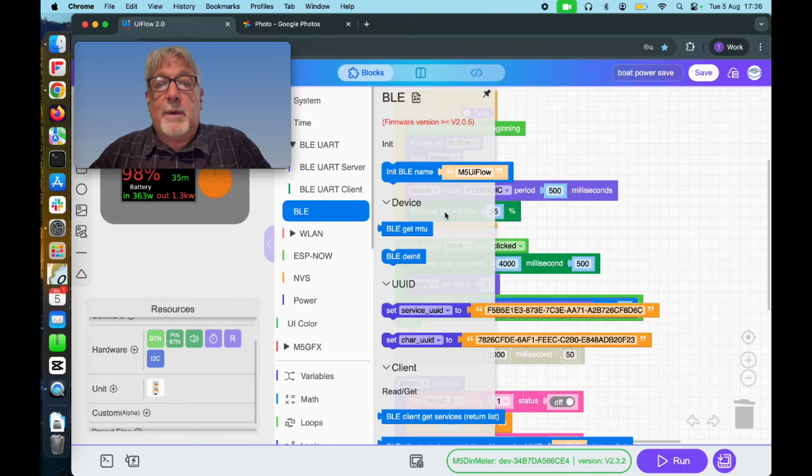And then that will be connecting to my Bluetti inverter, and I have some open source software which allows me to connect through Bluetooth or Wi-Fi to my Bluetti inverter and read all of its power levels, and also switch, say, the mains inverter on and off. So this will give me full control of the boat from a small sort of $25 device. It will give me battery and solar and timed access for any mains.